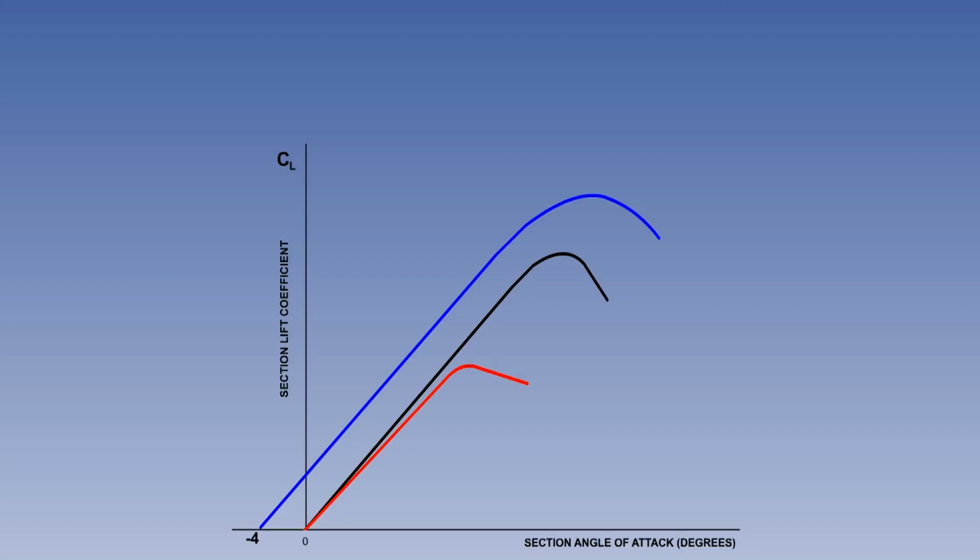The curve's move to the left indicates that, at 0 degrees angle of attack, the aerofoil is producing lift. Zero lift is achieved typically at around -4 degrees with the cambered aerofoil. The reason for this is that, even below 0 alpha, the camber creates a smaller stream tube cross-section than a symmetrical section, and therefore generates a small amount of lift.